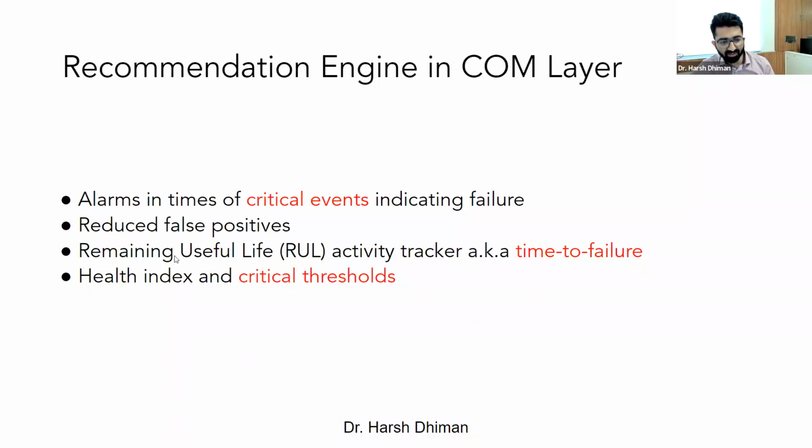The wind farm operator can track the RUL, and if he sees that the RUL is very near, then maybe some decisions can be taken for the gearbox. Maybe you can change the oil, maybe you can replace the bearings, and so on. Health index and critical thresholds, yes, again a very important aspect of the recommendation engine. Your recommendation engine should tell you what the current health index is. So health index is just a number. If the health index is close to 0, you would say that your turbine is close to failure. If health index is close to 1, it would indicate that the turbine is currently healthy.